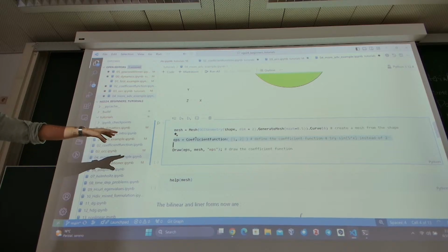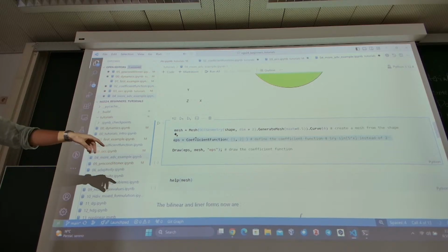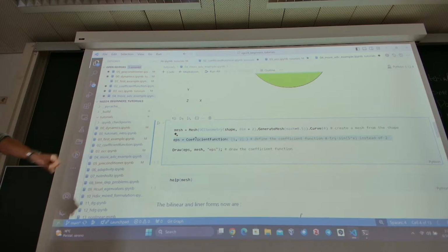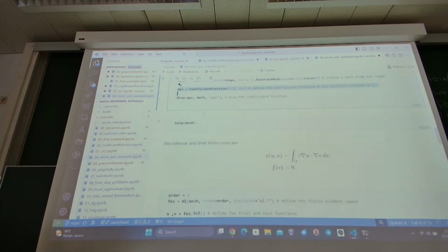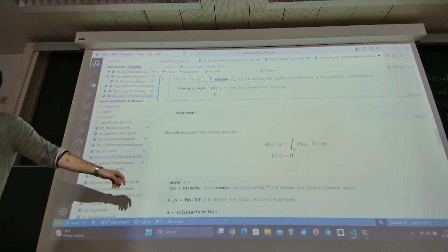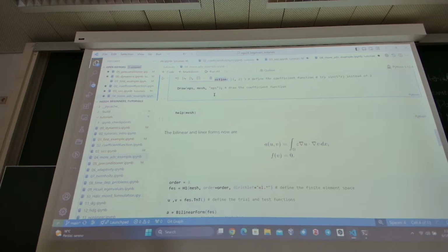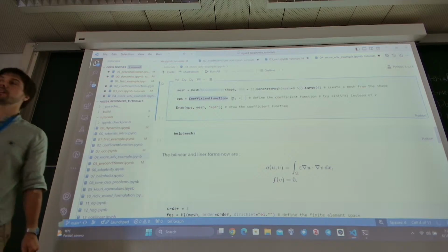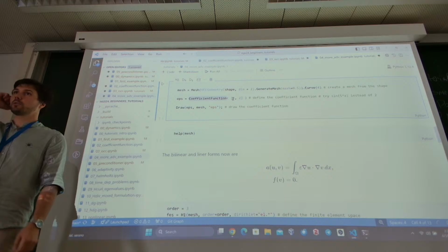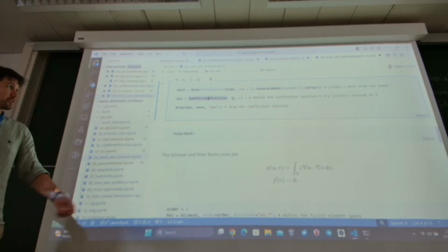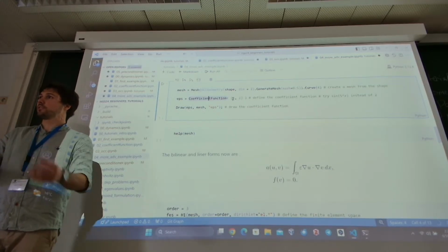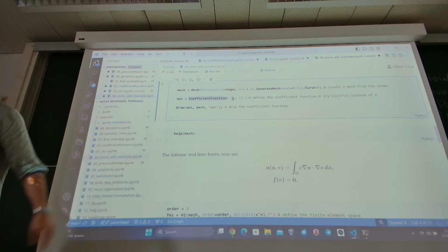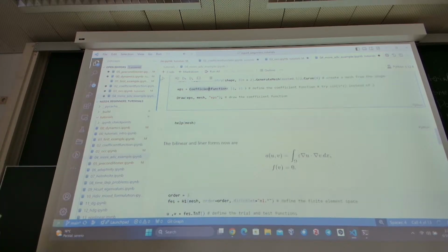Basically, here what I did, or what I want to do, is to specify some material coefficient function. This is going to change inside the updated version, but this is an old style. It has 1 in the first domain, 2 in the second domain, but then you have to remember the ordering. The problem is that when you create a complicated mesh, it could be that the order changes, so don't use this one, otherwise bad things can happen.